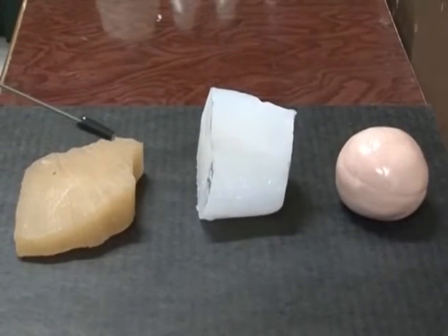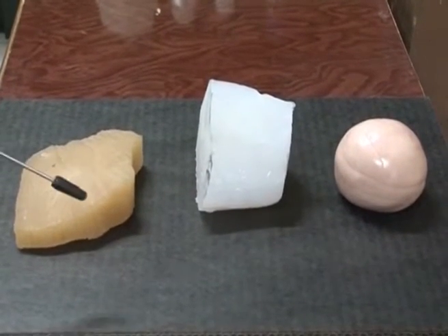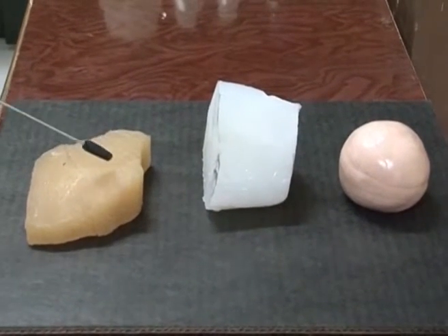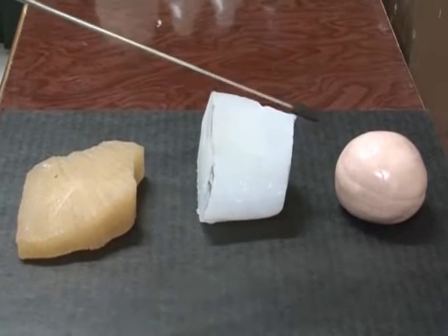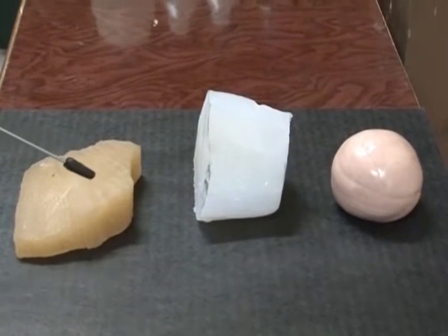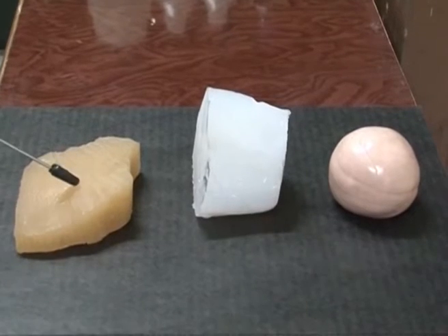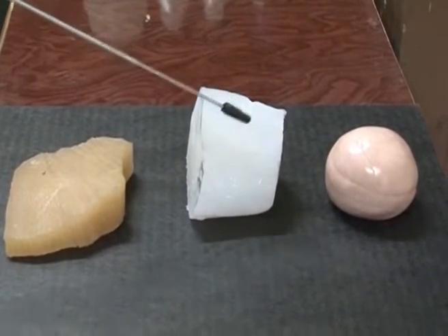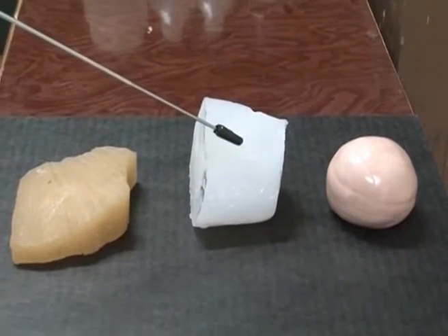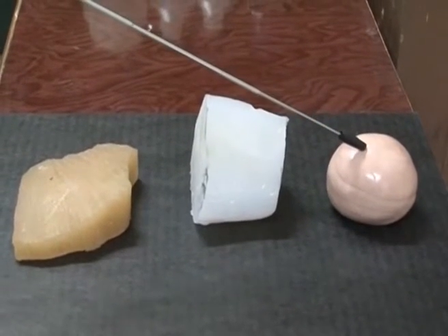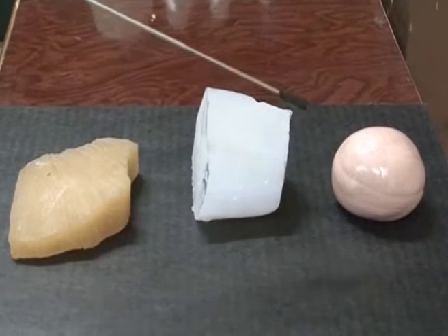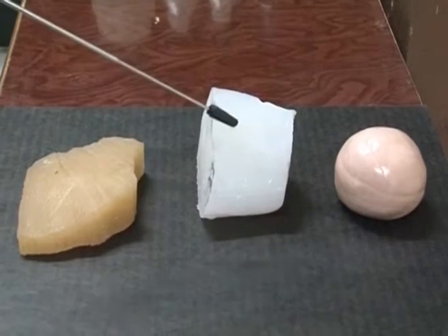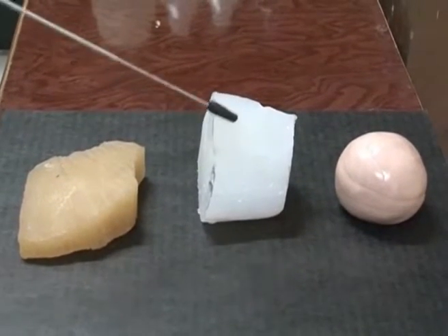The main ingredients in the polymer rheological abrasive medium are, the first one is polymer carrier. This is the base polymer carriers. In the base polymer carriers, we have specially made styrene polymer and we have silicone polymers. In the silicone polymers, we have two types. One is silicone and another one is silly-putty. The basic aim of using these polymer carriers is to hold the abrasive particle between the polymer chains flexibly.